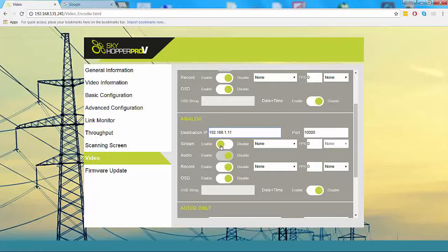If you want to stream the video, you will enable the streaming, and you will want to select your camera resolution. If you're using both HDMI and analog cameras, the resolution of one camera will affect the other because it divides the channel's throughput. Next, you will select the FPS, the frames per second. Commonly, you're selecting around 25 or 30 frames per second. Finally, you will select the video stream quality.